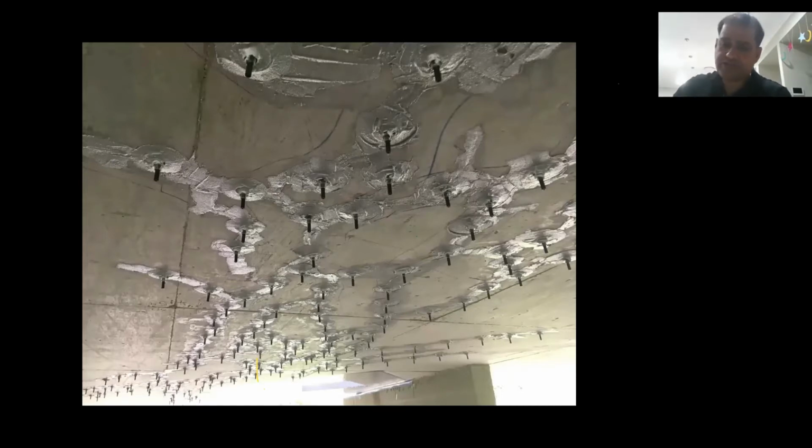Low viscosity epoxy is just like water. It's such a low viscosity that the moment you apply pressure with a gun, it will find its way inside and travel within the crack and concrete matrix and fill all the gaps. And it will reinstate the structure to its original strength. This is how it ended up after grinding it off, finishing the injection and applying anti-chloride, anti-carbonation coatings.